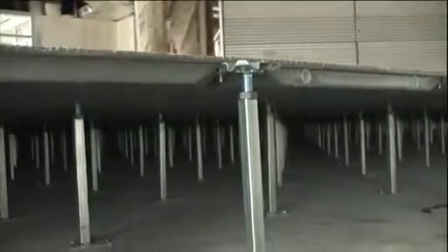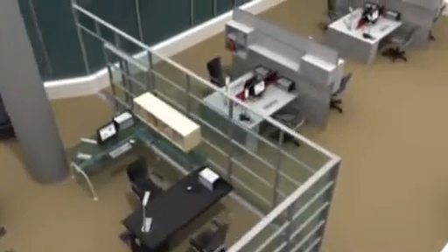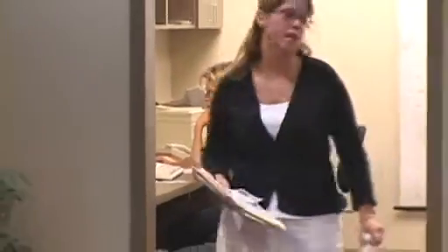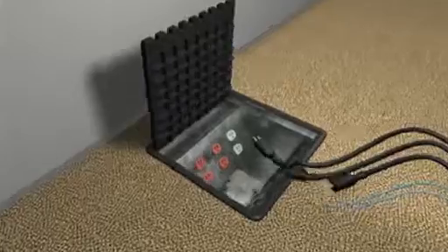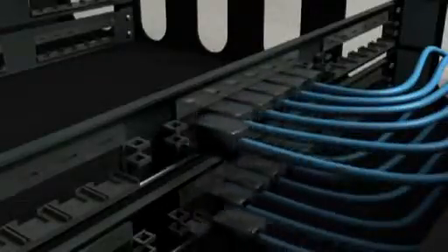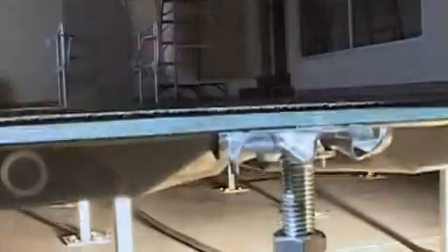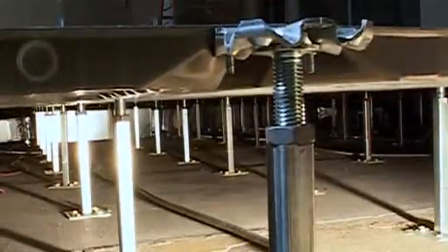Underfloor air delivery is a byproduct of the development of raised access floors. In the beginning, they were used primarily for data centers, computer rooms, and similar facilities. Human comfort was not a primary concern. As technology became an increasingly integral part of business, and the need to gain access to building infrastructure, such as electrical, phone, and data lines throughout the business environment grew, raised access floors allowed unfettered pathways to route and reroute cable. All raised access floors have removable panels supported by grids of pedestals of various heights.